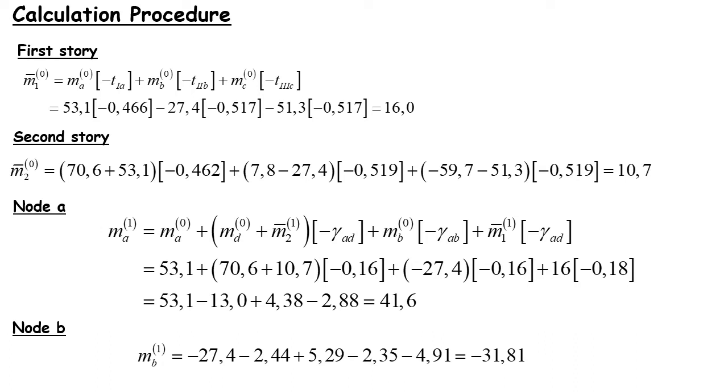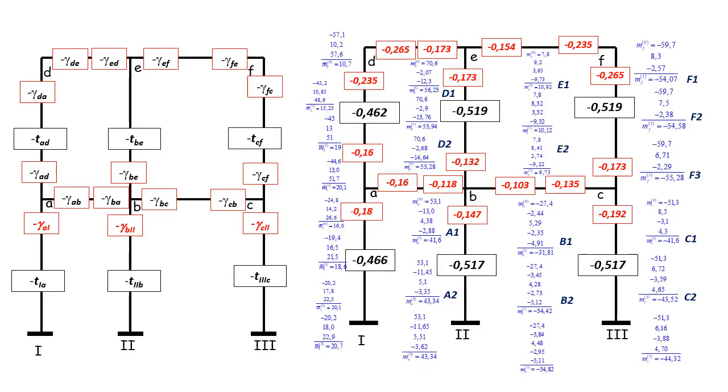Then by utilizing the moment rotation bar, we can calculate every moment rotation at the first iteration in every node E, B, C, D, and so on. The simple way you can do in this method is to write down all your calculation iterations in every node of the frame structure system.